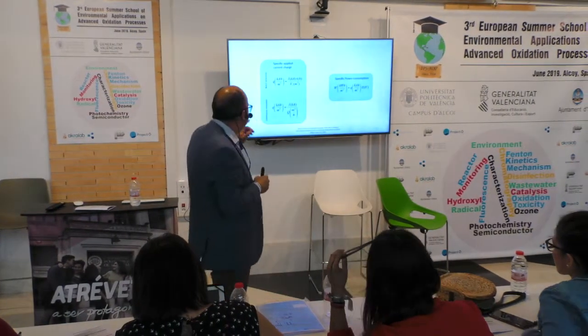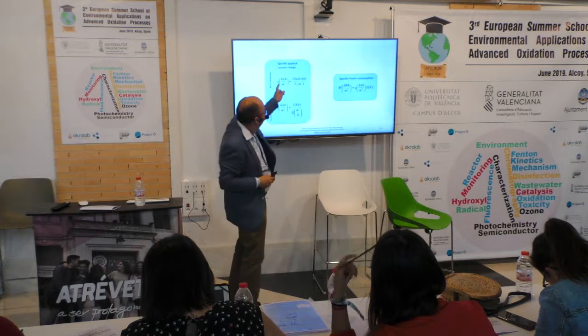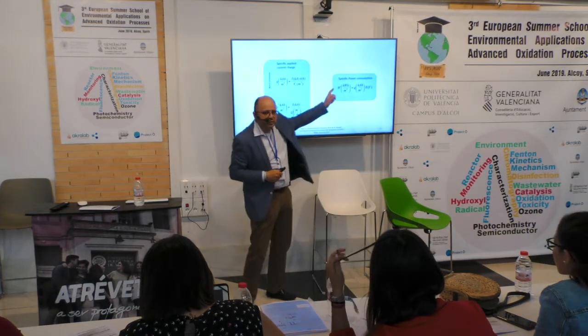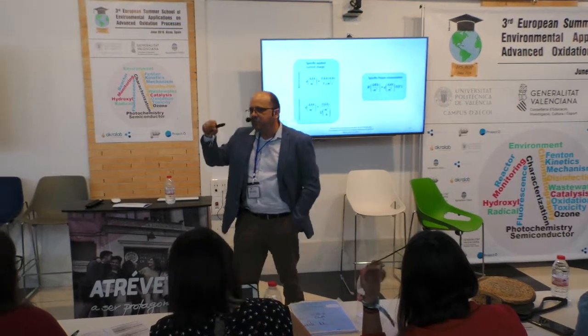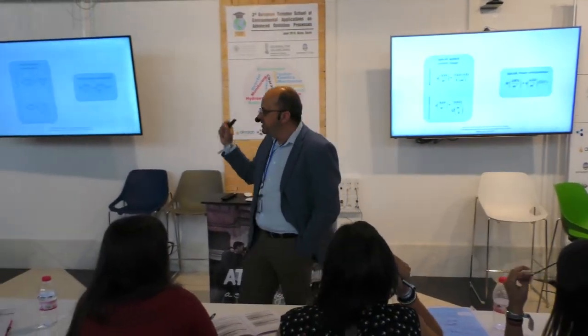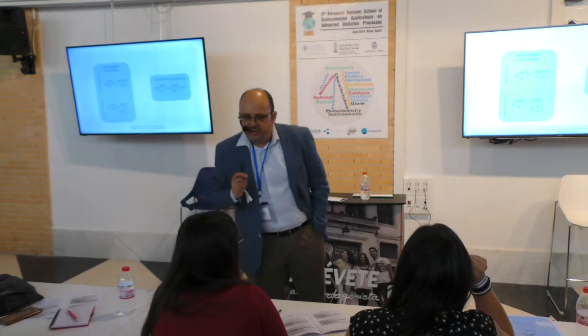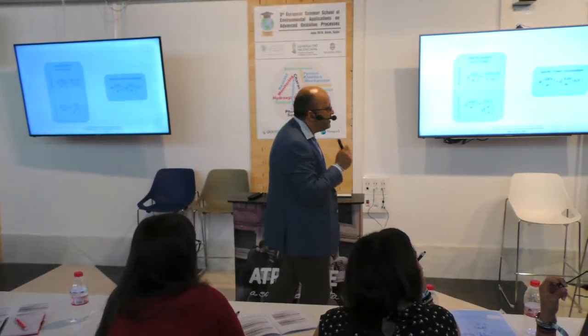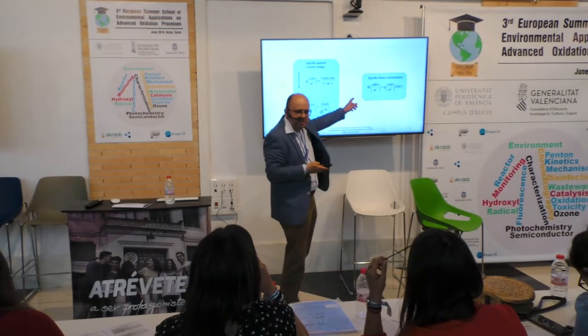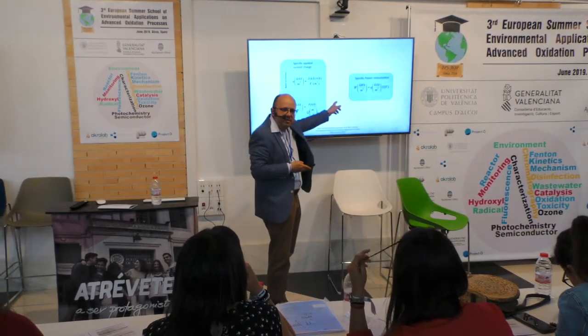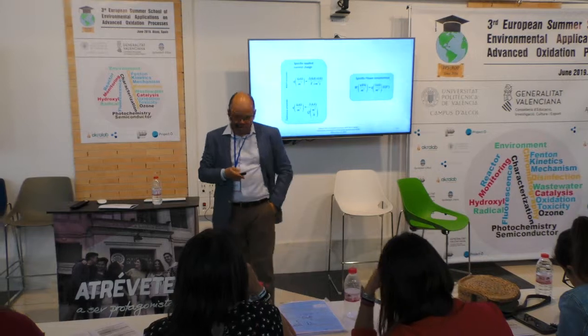And this specific applied current charge is related to the specific power consumption by multiplying this value by the cell voltage. This means that I can easily calculate the power consumption of an electrochemical process by using this equation.